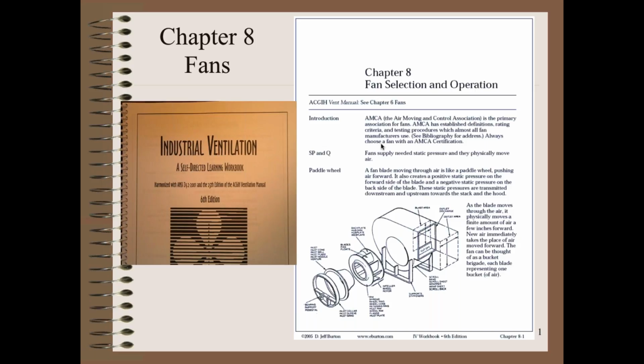We're the ones that design this system, and we say that on the suction side of this fan, we need this suction pressure, -4 inches of water, in order to accomplish what we need all the way back through all the contractions, elbows, and all the way back to the hood. That's what we need at that point to overcome all the losses in the system and deliver what we need at the hood. That's really where we need the performance, at the hood. But we lose efficiency all the way through, so this has to be able to make up for that.